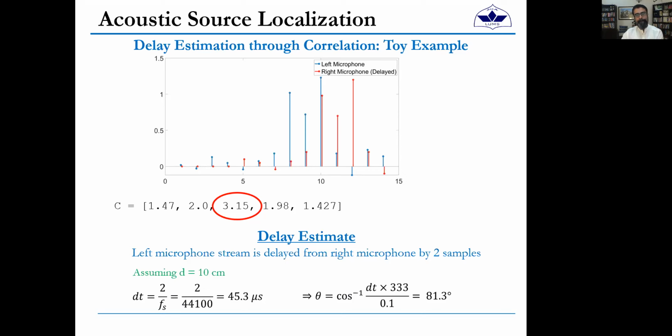Okay. So can I ask the question? Yes, go ahead. Can you please tell why did we divide 2 by fs to calculate dt? You see, this goes back to lab number 2, in which I said that these signals are continuous time and they are sampled at a certain sampling frequency. So how much distance in time, in seconds, is there between two samples? That's 1 upon the sampling frequency, right? Yes, which is called the time period.